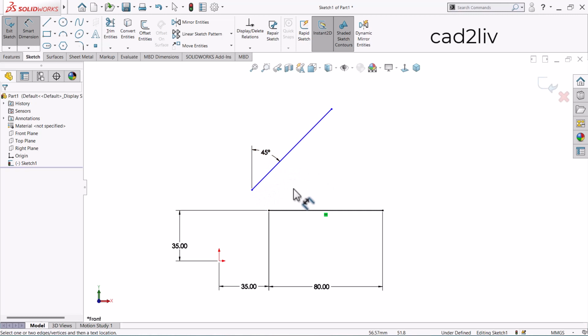Now, the exercise for you, like take a snapshot of this, do start making in the SolidWorks, and then give the dimensioning to this and make it fully defined. Like in this, we need 3 to 4 dimension. First one is vertical, then horizontal, then just define this point's location from the origin. In this way, this is going to be get fully defined. Just comment below once you have done this exercise.